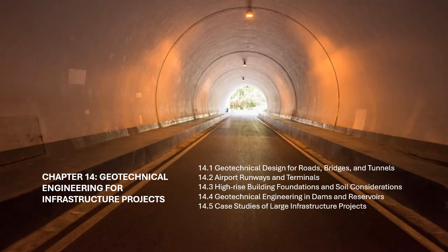4.2.3 Geotechnical Challenges in Airport Infrastructure. The construction of airport runways and terminals presents unique challenges for geotechnical engineers. Heavy and repetitive loading. Both runways and terminals experience heavy, repetitive loads due to the constant movement of aircraft and passengers. This requires careful consideration of pavement design, foundation stability, and soil compaction to avoid premature failure or deformation.